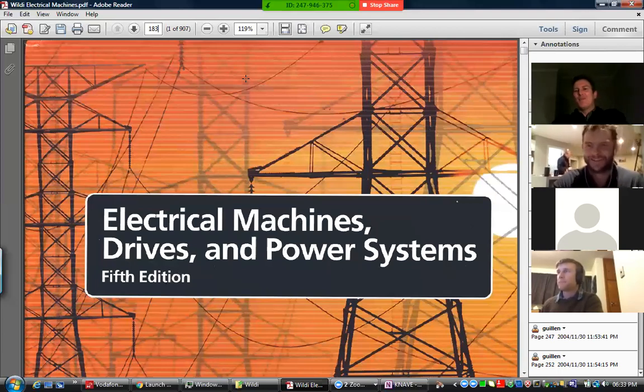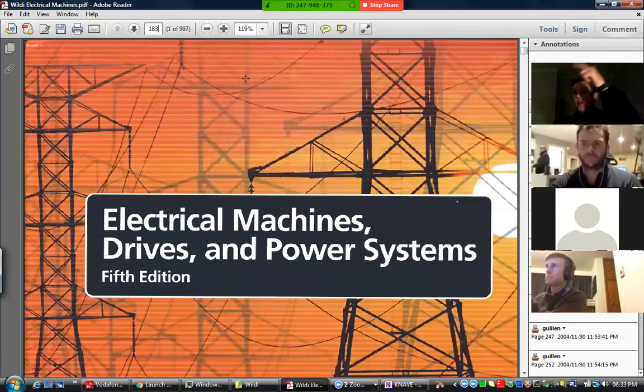As the motor spins, as you flick that switch, the thing will still be spinning. When it spins, it still generates an EMF. That EMF will try to drive current through the armature circuit, which now includes resistors. So by applying some basic Ohm's law, you can work it out, and I think I gave a relationship between current and torque as well. See what you can do.